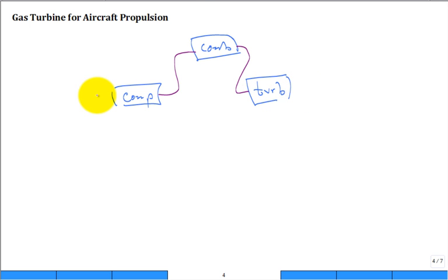But what do we have here, especially if you're flying at high speed? The speed of the air coming into the compressor could be too fast. So I'd like to introduce a new device that will have the purpose of slowing the speed down, because it could come in at the very front of the engine too fast to just let it go into the compressor. So what engineering device do I put in the... Perfect, it's a diffuser.